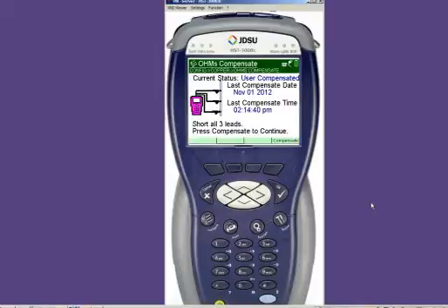Here, you just follow the directions: short all three leads, clip them all three together, and press F4 to compensate. This gets rid of any resistance in the test leads themselves, right? Zeroing the meter out, we used to call it.